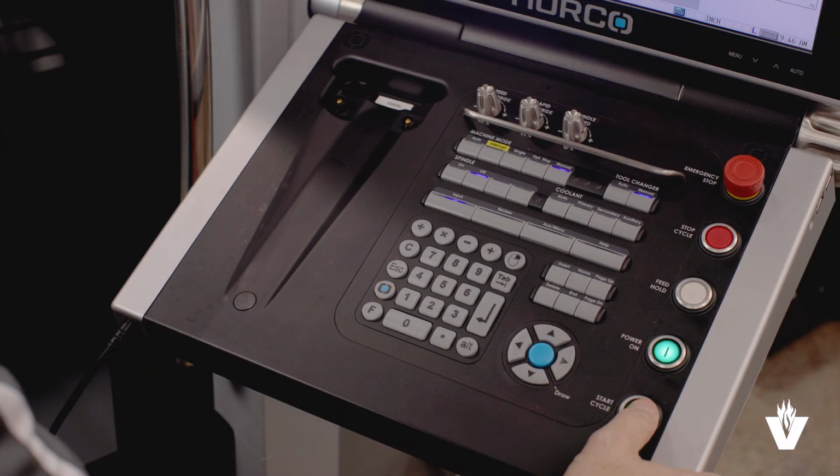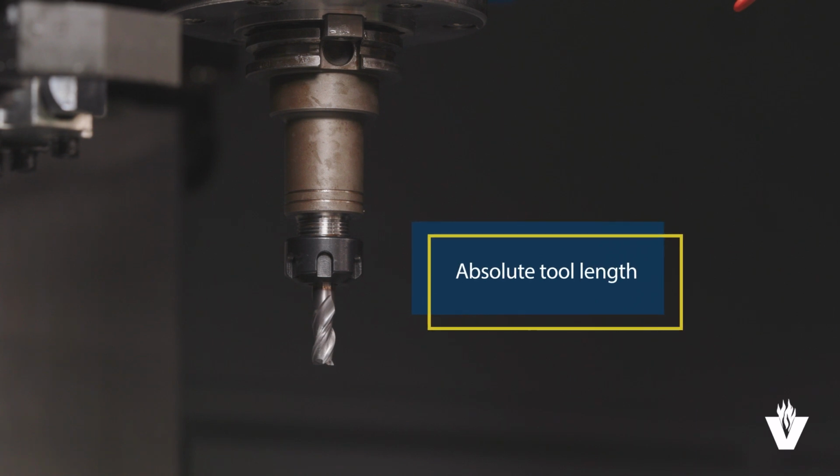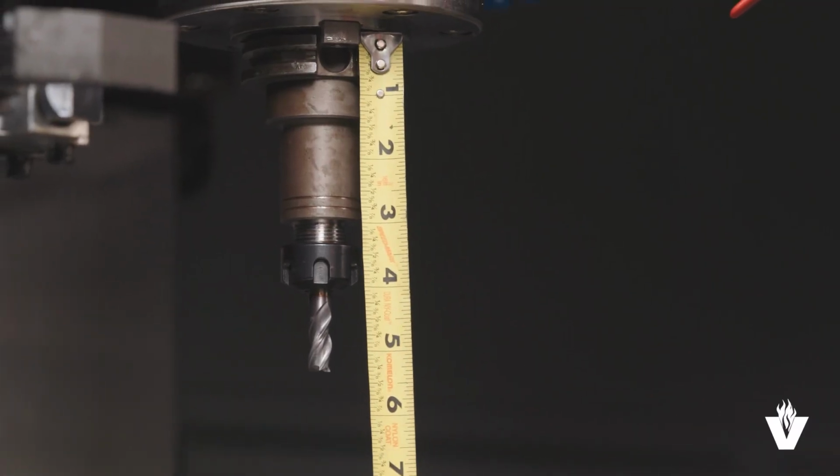This value should represent the positive length of the tool projecting from the spindle. That is known as our absolute tool length. If you take a tape measure and measure from your spindle nose to the tip of your tool, that distance should equal the value that is stored. The machine has used the Z reference, our touch-off device, and the machine's Z position to establish this length.